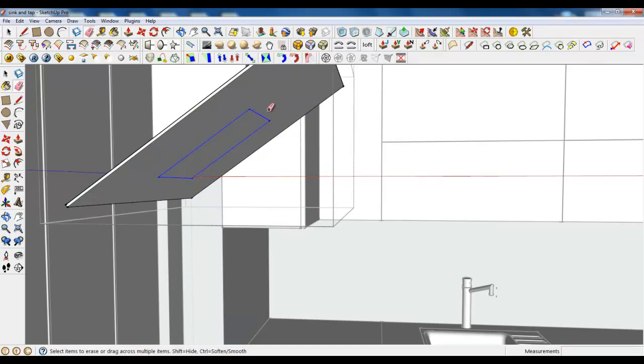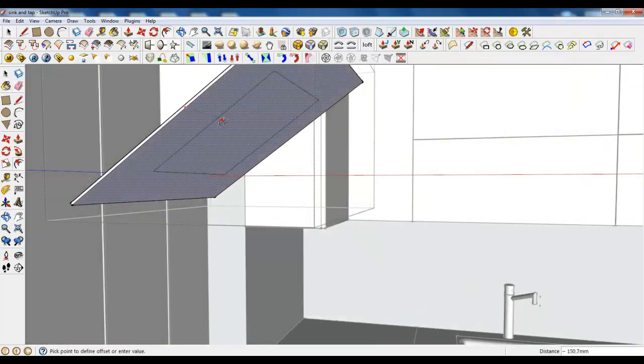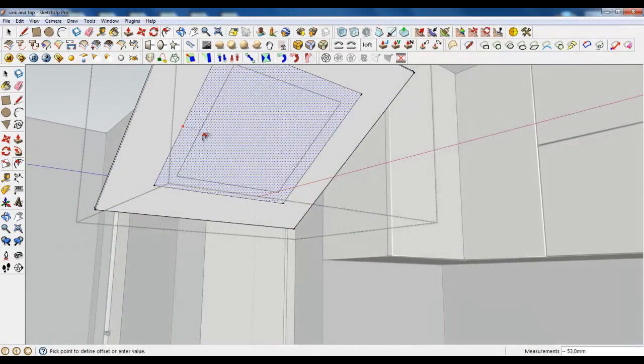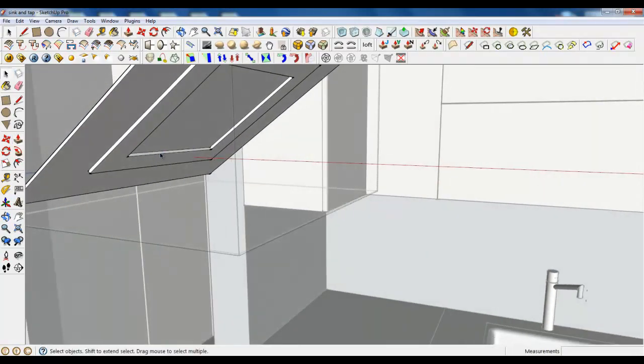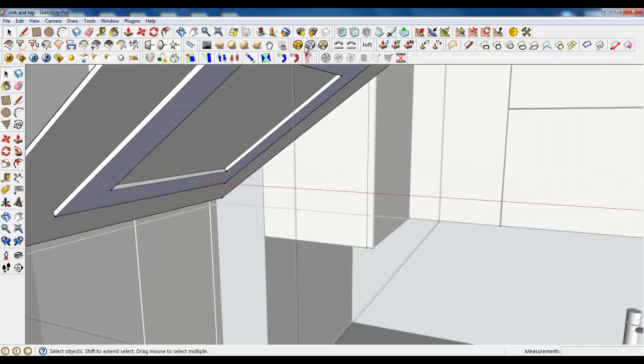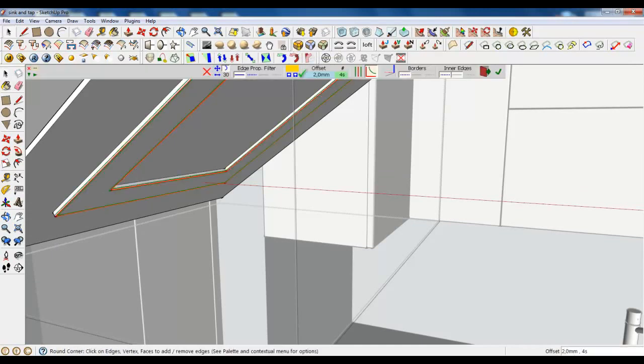Delete necessary lines, and create another offset. Type in 115 and make another offset and type in 60. Extrude and use your round corners in 3D, 2 mm and 4 segments.